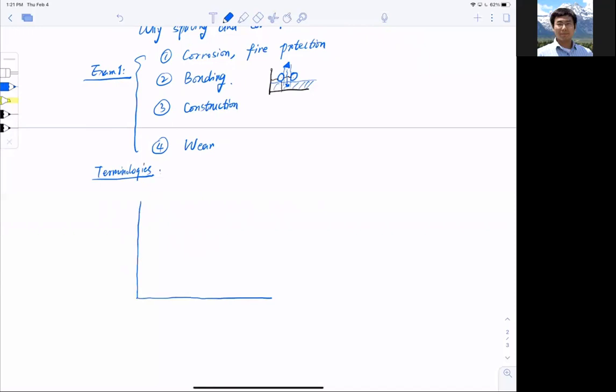Imagine I start to put reinforcement in it. First things first, what you will see from outside in is the stirrups. It's the stirrups: shear reinforcement, transverse reinforcement. The stirrups go just like this and have a curvature. I don't want anybody to draw a straight angle here. If you draw a straight angle, 0 points for you. So it's always a curvature.